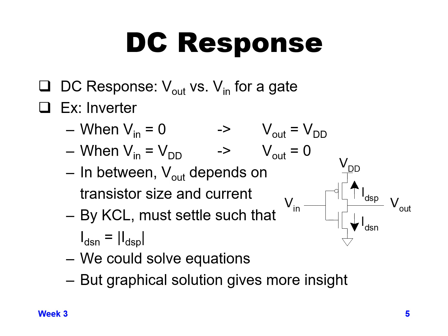And by Kirchhoff's current law, the current must eventually settle so that the current through the drain of the NMOS and the current through the drain to source of the PMOS equal each other. This is assuming that the current going to whatever load you have is 0, and so we need to solve for those equations.